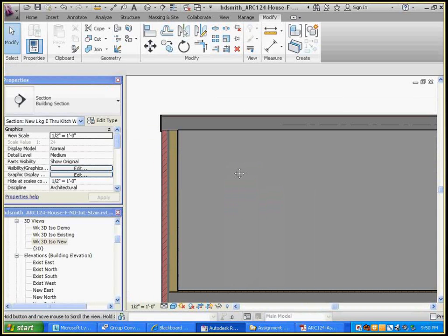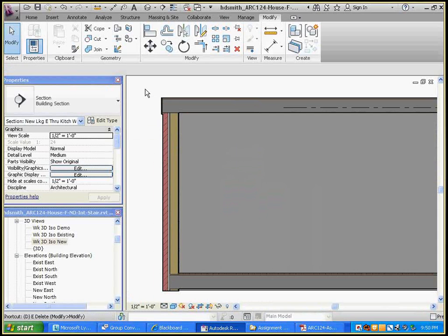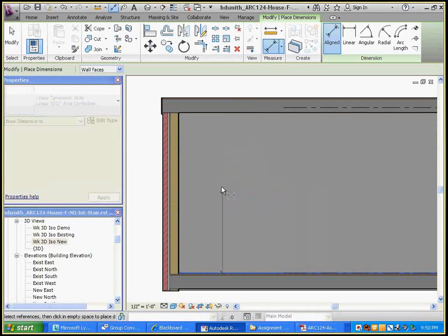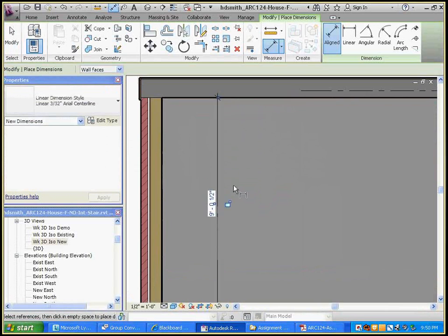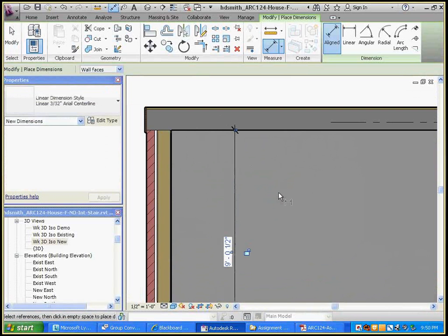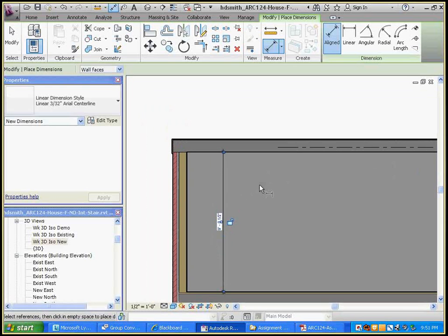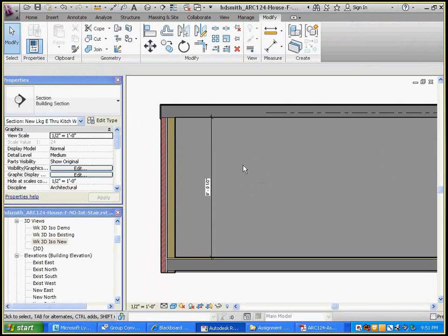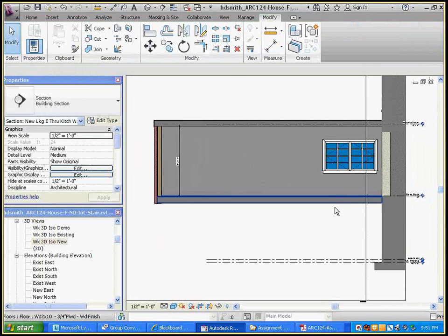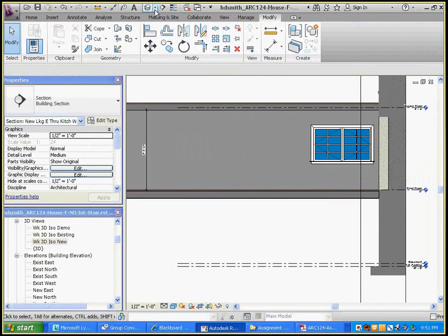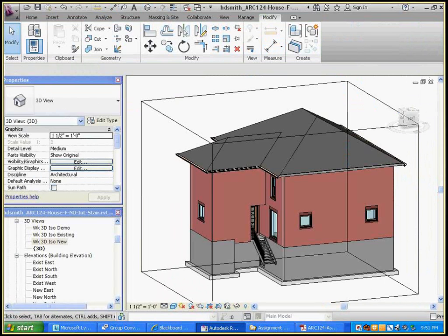And if I want to measure my theoretical ceiling height here, I can put a dimension from there to the joist, the rafter, 9 foot 1/2, and in assignment F2 next week, we're going to put in ceilings. We'll nail a 1/2-inch chipboard, and we'll have a nice 9-foot ceiling. So the dimensions have worked out very comfortably for us. So I'm going to go ahead and burn this recording here.